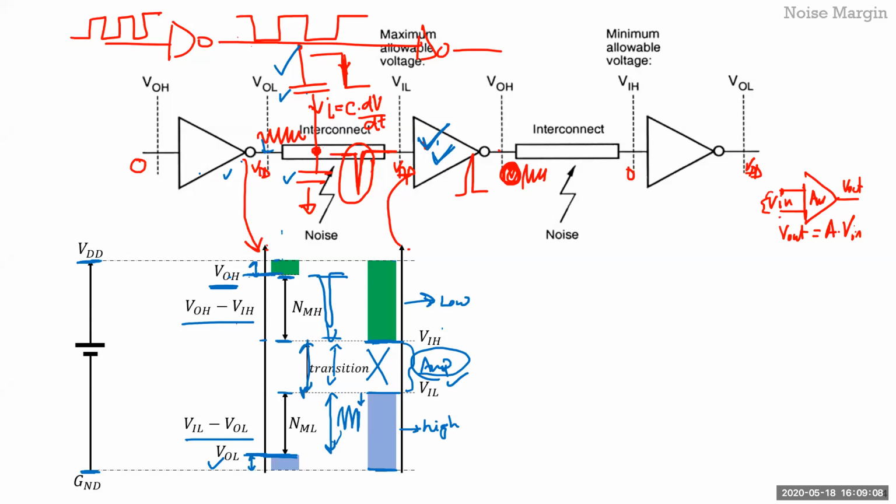So, is there any relation between the noise margin NMH and NML? Like in the design, something like NMH should be greater or NML should be greater. Well, there are certain constraints, right? I mean, it's obvious from here. For example, your NMH plus NML cannot be greater than VDD. So they have to be within the supply, right? That's one constraint, but usually it is much less than that. So that is probably the only constraint.